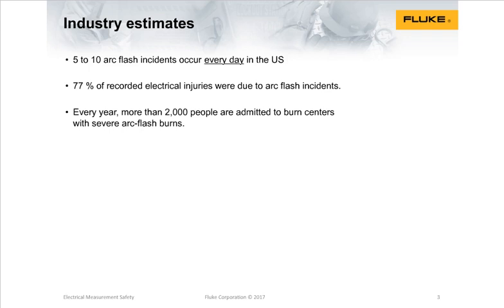An arc flash can happen from a short circuit between phases, or even phase to ground. It can happen even in a residential panel, as well as commercial or any other source that you may have. The amount of incident energy and the amount of current upstream from the circuit protection, before clearing happens, will govern how long this arc flash stays in effect. And 77% of the recorded electrical injuries were due to arc flash incidents.